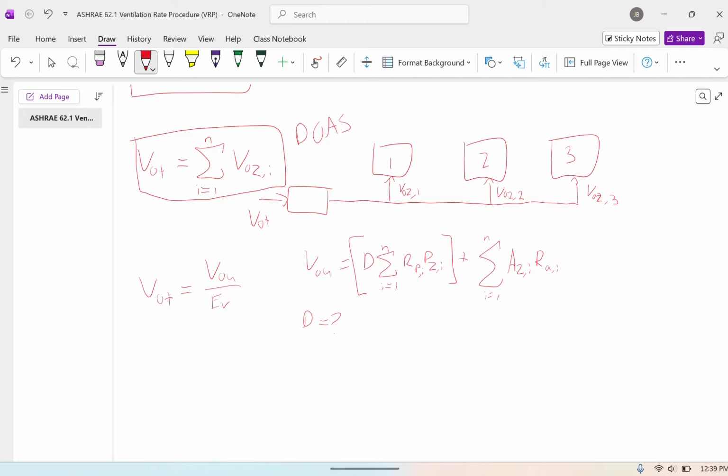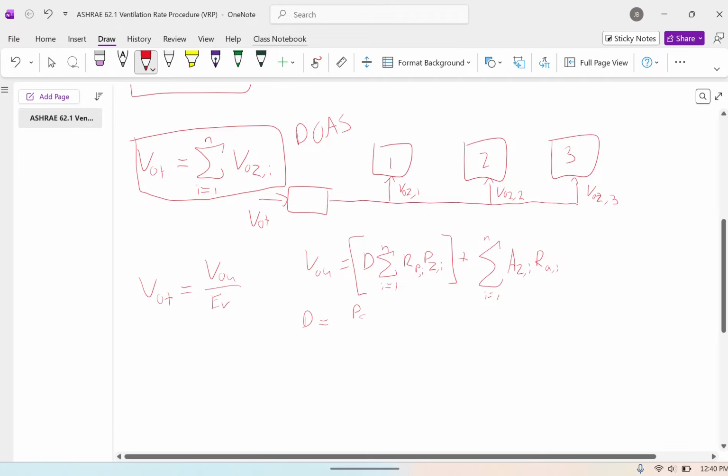Each of those spaces would have its maximum occupancy, including the boardroom, but the people that would be in the boardroom are the same people that would be in the offices and cubicles. They would leave those spaces, come to the boardroom, and then they would leave the boardroom and go back to their other space. So it's the same occupants, but they would be double counted if we were not using this diversity factor. And luckily, the calculation of the diversity factor is quite simple.